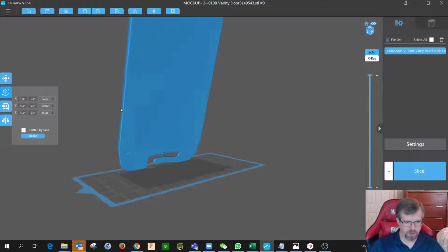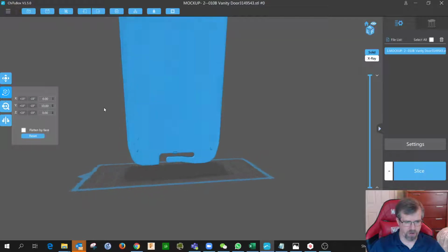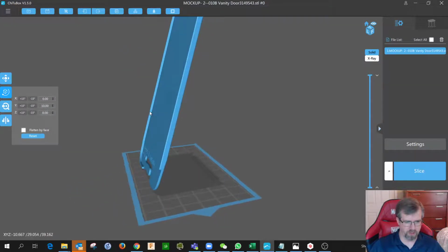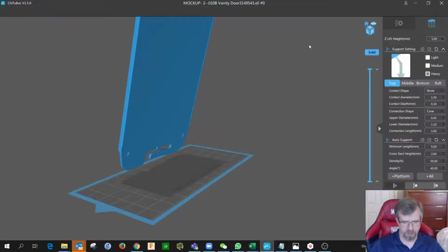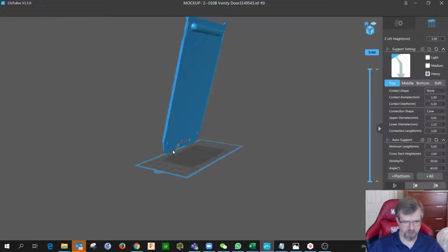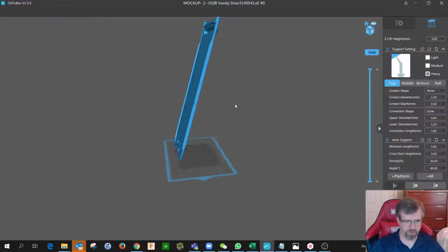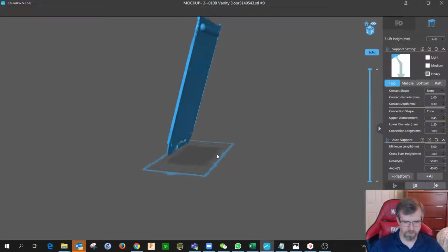So in this case, I'm going to start by lifting this part up a few millimeters and put a base of supports underneath it. Now the support area is over in here, so all you've got to do is click that. Now we still have our object highlighted. You'll see it automatically lifted up, because last time I printed, I told it to lift this object 5 millimeters off from the bed. So you can change that to whatever you want. You could try to go very small, but you need a little bit of room for your supports to have a spot to get placed in here.